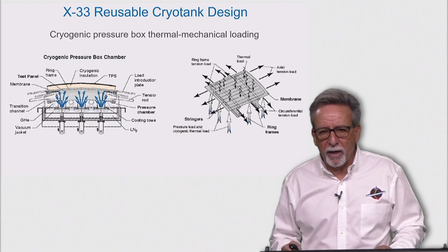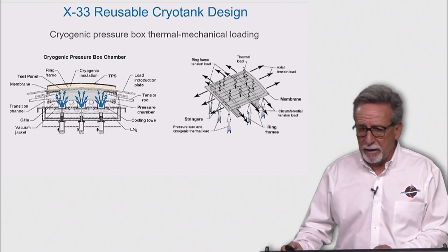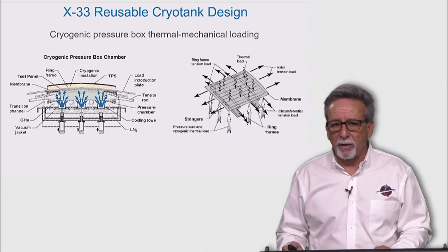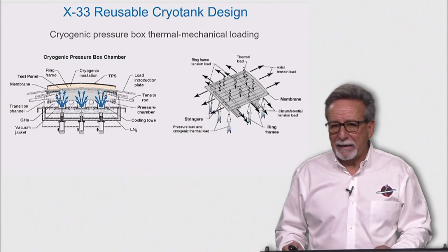A quartz lamp heater array is also used to heat the external surface of the specimen to maximum temperatures of 1,000 degrees Fahrenheit. The heater array is flat and has 8 symmetric zones that can be individually controlled to evenly heat specimens of various curvatures.